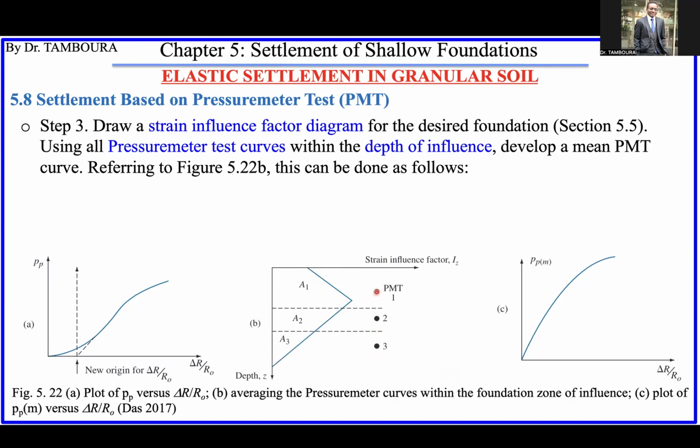You don't need any pressuremeter test below that. After drawing this strain influence factor diagram, you know where the limit of influence is.